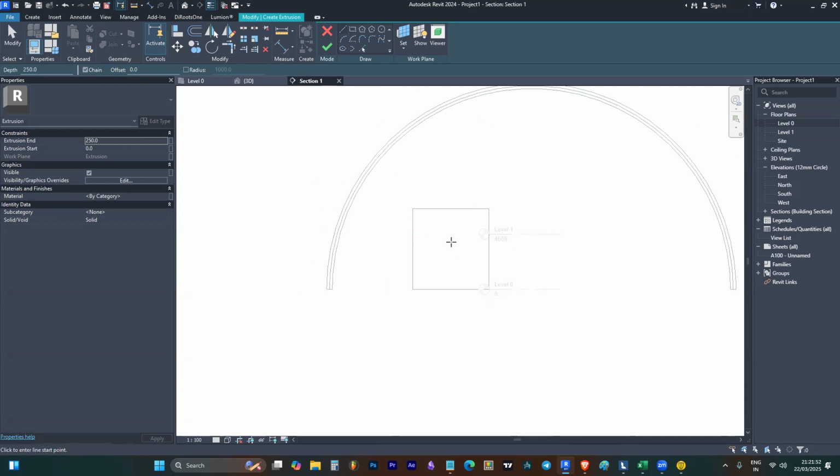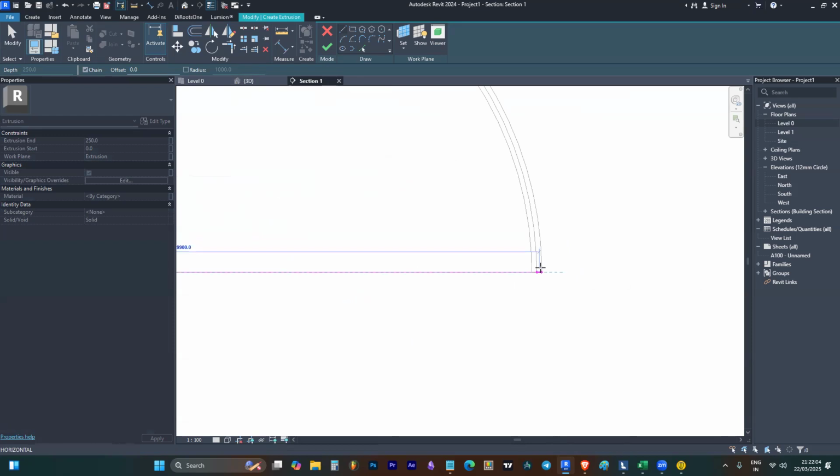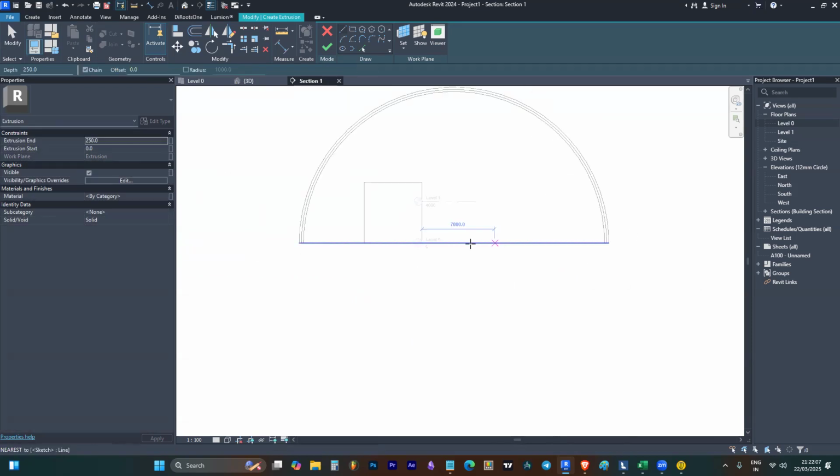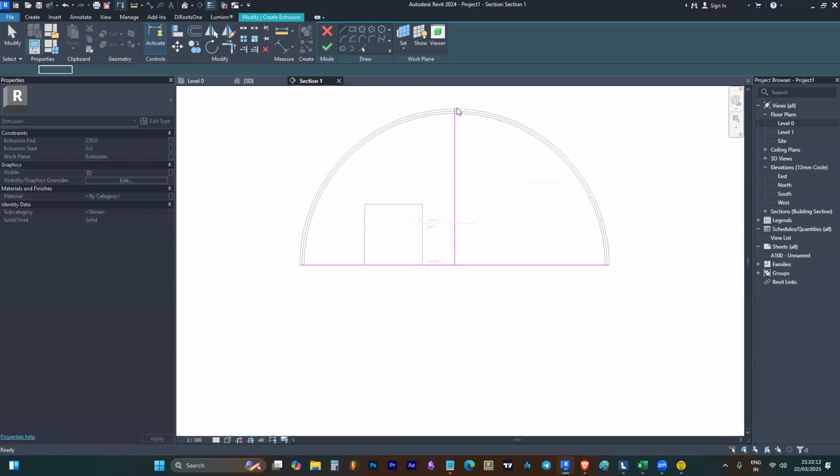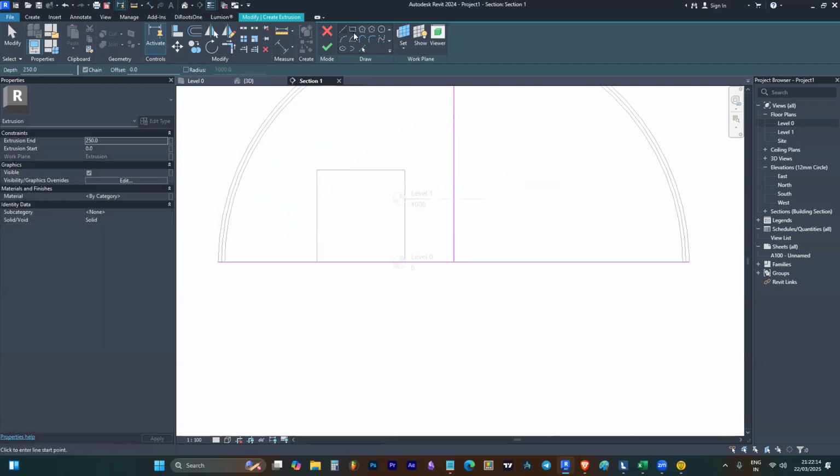Put the extrusion we have created for the face. Now let me create a void to cut open the entrance. For that, I have to get the center point of the dome structure. So this will be the center one. Now here I can provide an arch kind of opening. Let me try to create one arch. Cut an arc.